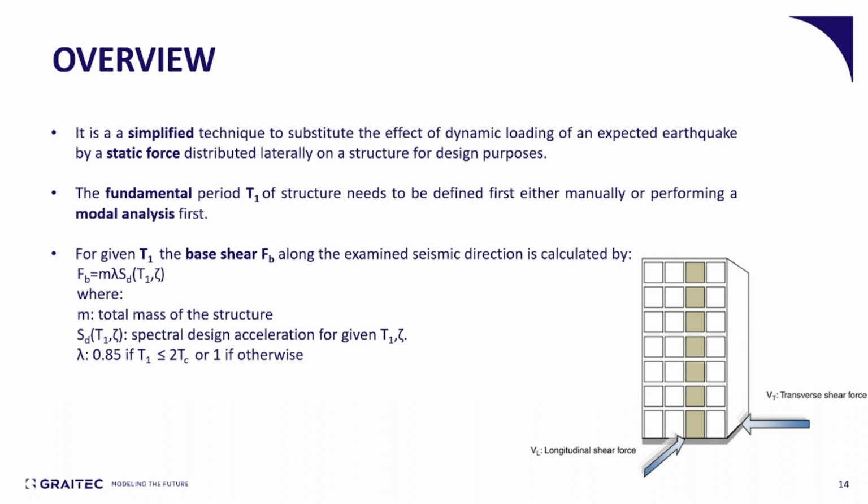And for this given fundamental period, we calculate the base shear FB along the examined seismic direction, let's say, for example, the X direction. So the base shear can be calculated by this equation, where m is the total mass of the structure, Sd is the spectral acceleration, either calculated by the elastic or the inelastic spectrum, and lambda is a parameter that follows this rule, which is either 0.85 or 1.